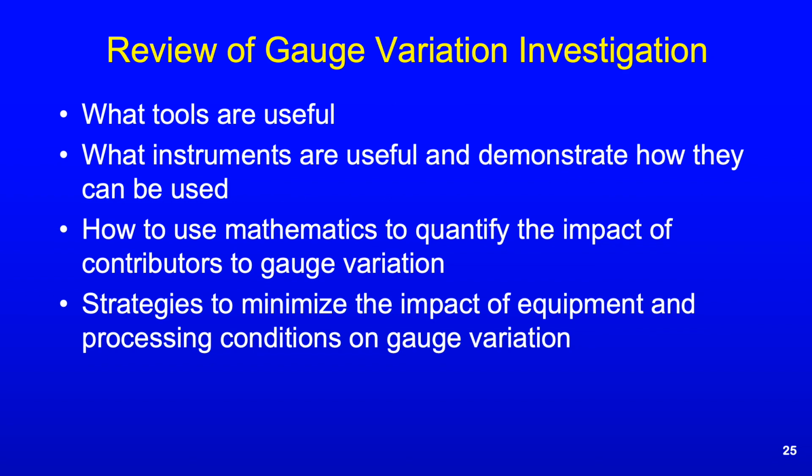So just to review, in this tutorial, what I've done is I've discussed what tools I find are useful when evaluating the performance of film lines. I've included the fact that I use a cell phone to take pictures and videos, an infrared camera attachment to find unusual temperature variations where there shouldn't be, and good quality gauge profilers to measure gauge variation accurately.